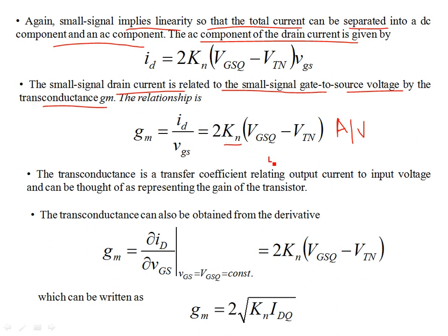Okay, what it says is that your output drain current, as we'll see in the small signal circuit, is gm, which is the transconductance gain, times VGS. As you see, the units are in amps per volt. The output drain current due to the input VGS, which is an alternating, sinusoidal, time varying source, when multiplied with the transconductance gain gm, produces a linear AC current, id.